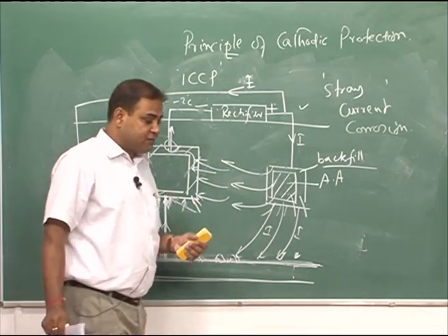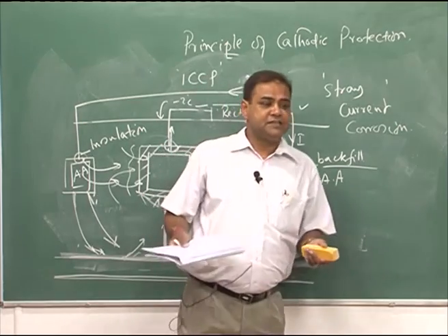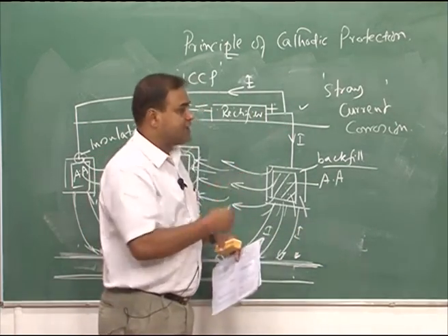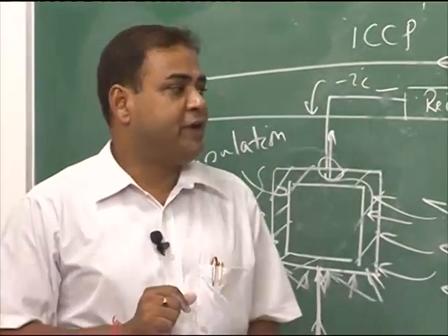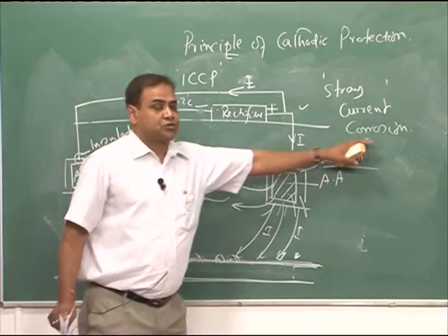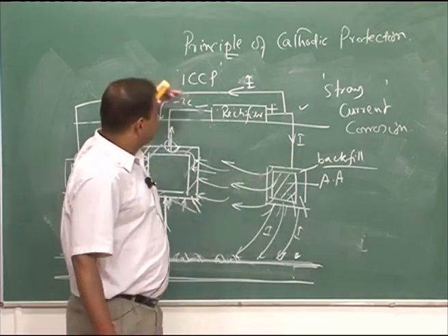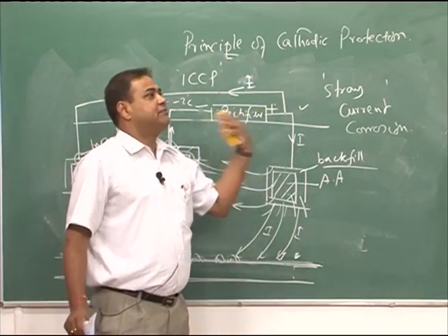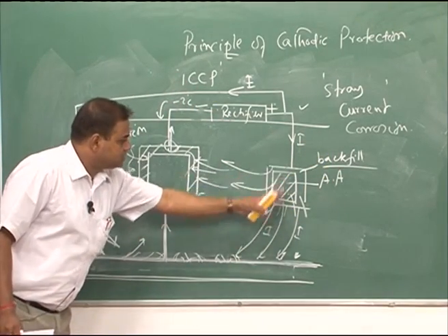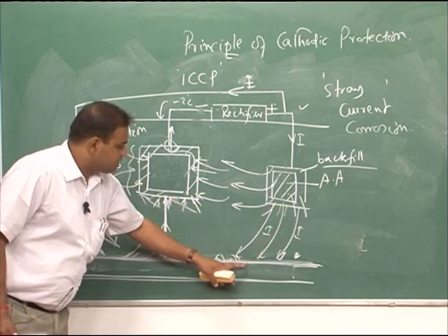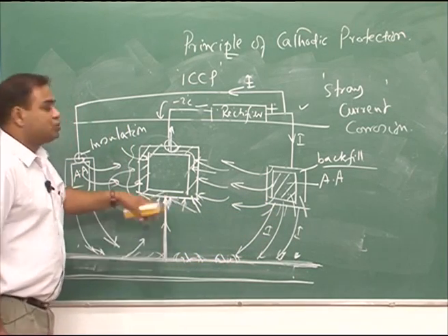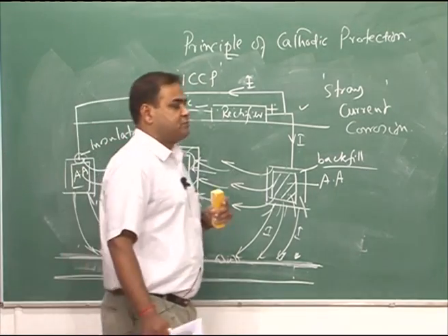Another example is in cities where you have tram line, okay, below the tram line, if a water pipe is going, that water pipe can also come under stray current corrosion, because the tram line, the top part, when it goes, that time it develops a potential field and the current will enter into the water pipeline and it leaves the pipeline and goes to another surrounding metal object.